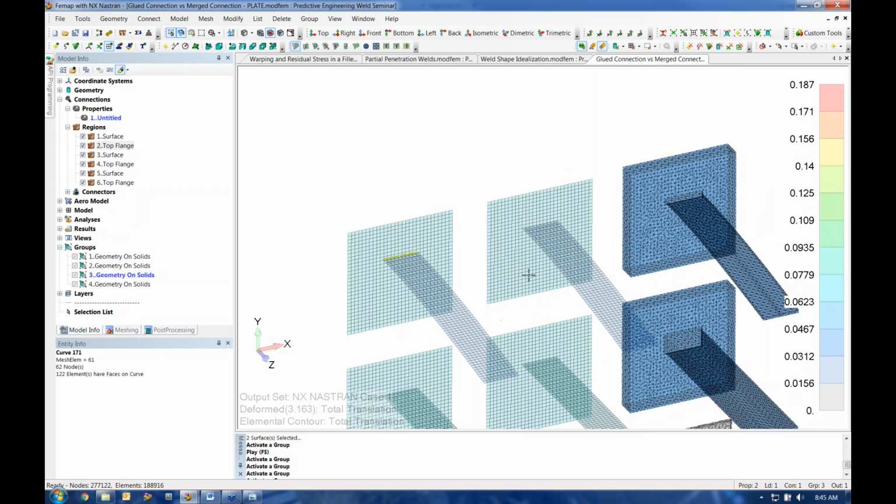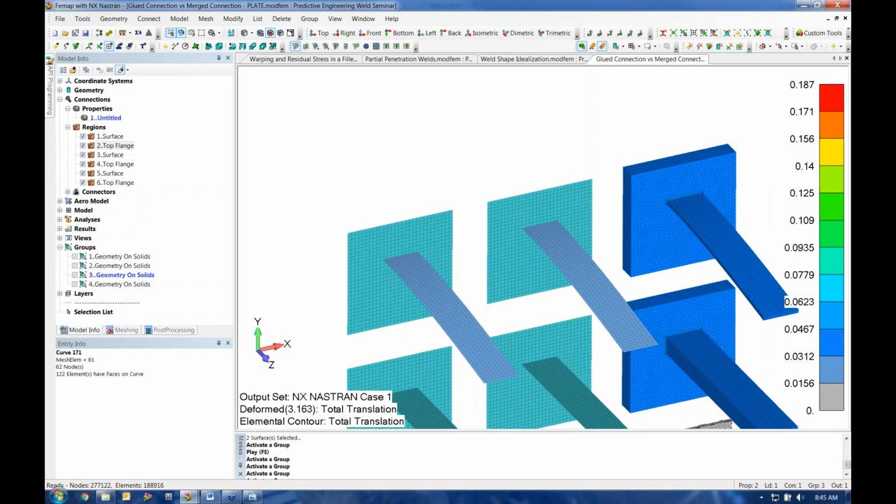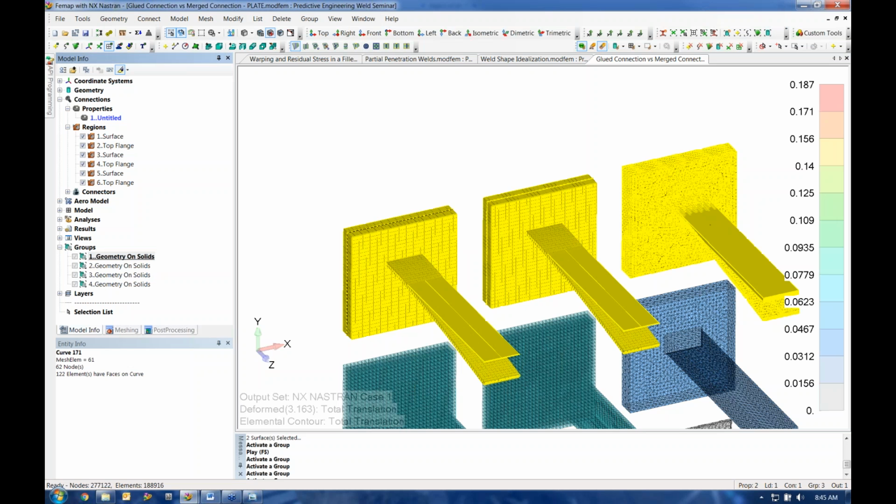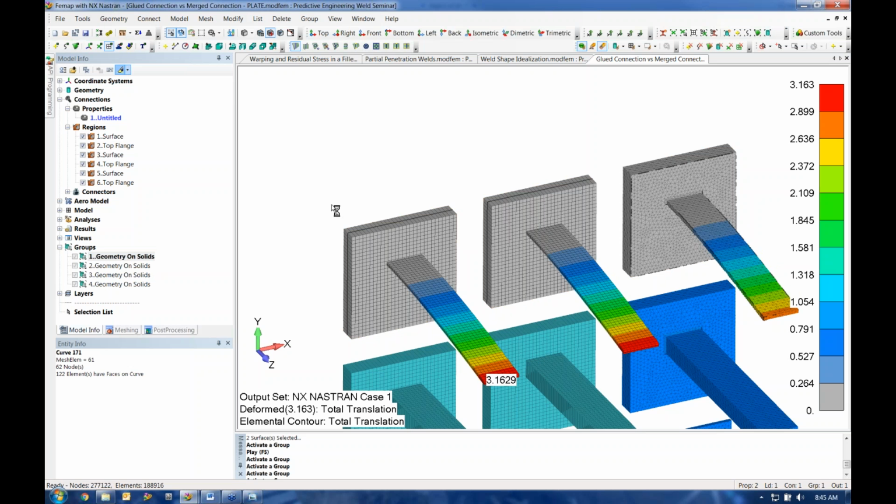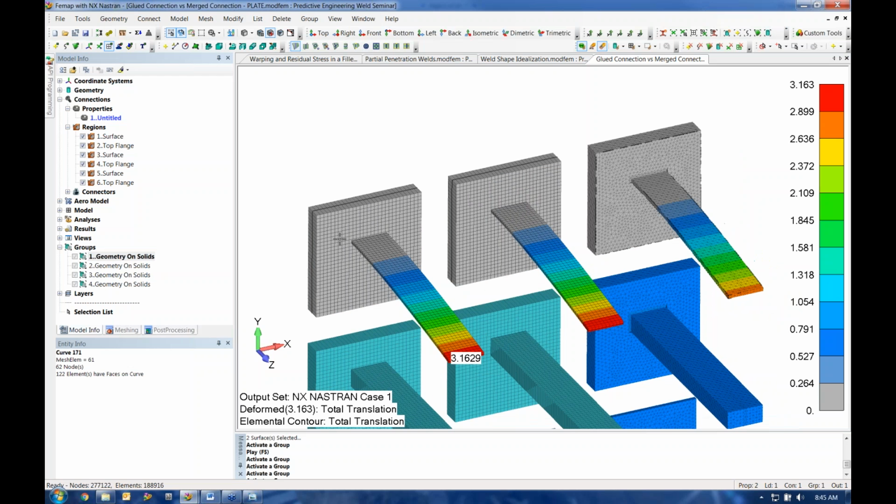So does it really matter which method we use? Do we get pretty similar results? Like I said, I set up an array of different thicknesses here, and I found that with a thick back plate and attaching a thin bar here, in terms of deflections, both methods matched up with the solid element pretty well. I didn't see a huge difference.